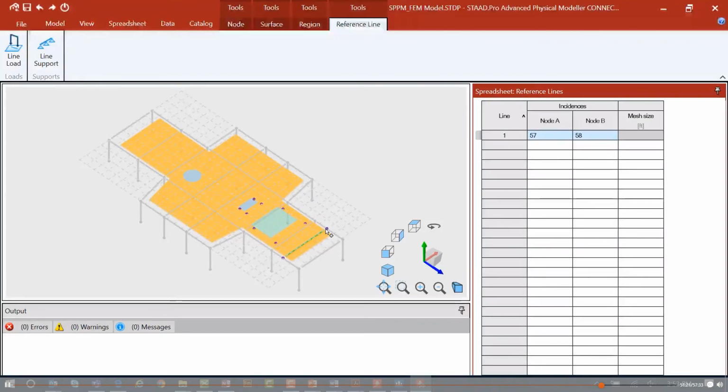And also, again, if you want a particular density point, maybe you're adding a point load somewhere within this system, for example, you could just add a node within the area and it will detail it accordingly to make sure that node corresponds with the finite element mesh that's eventually going to happen.